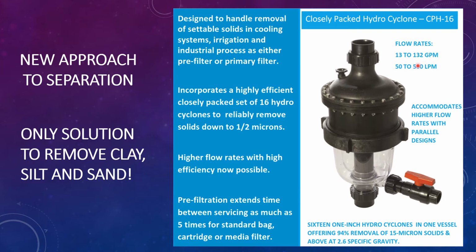Anything outside that dramatically impacts either the pressure loss or the ability to move solids. And this can be manifolded, as we'll see, to provide higher flow rates. And if we use this in a prefiltration, or as a primary filtration, we not only remove those solids to protect the filter, but also the system. And so we might see at least a 5-time decrease in high solids loading of the filter backwash.